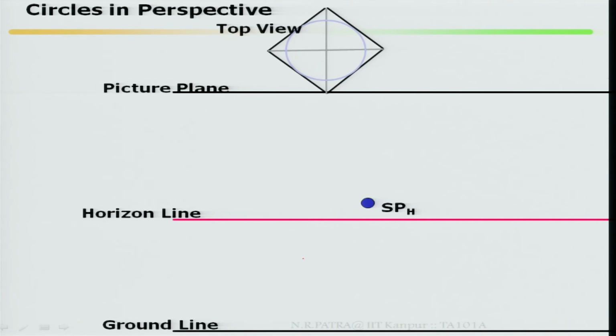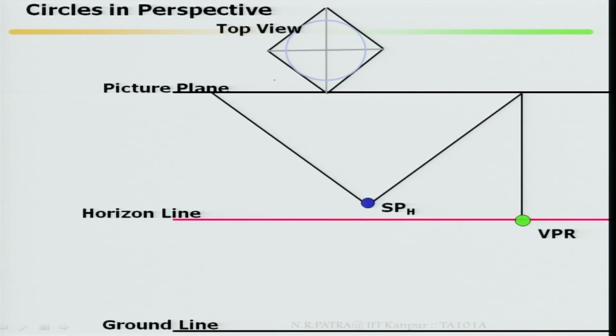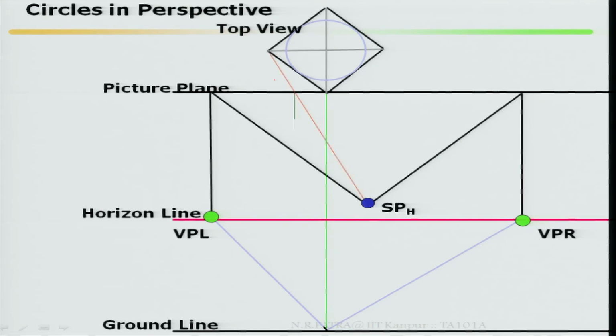In this case this is an angular perspective. How many vanishing points are you supposed to get? It is 2 vanishing points. With this surface, from here, draw here; with this surface you can take the vanishing point left as well as the vanishing point right. Then once you locate them, project it back, and from here join the vanishing point left, and from here you join the vanishing point right. Then take it, look at your outer edge.